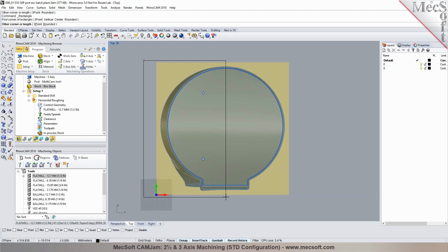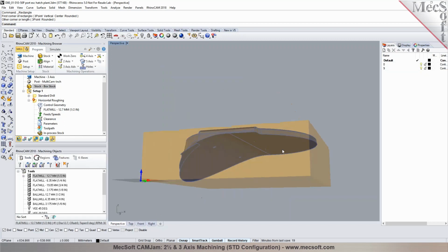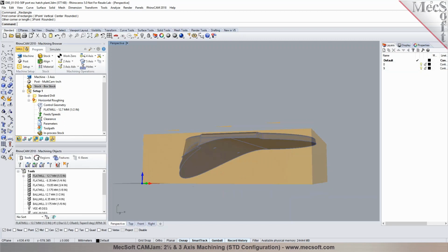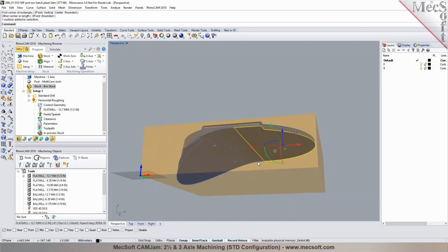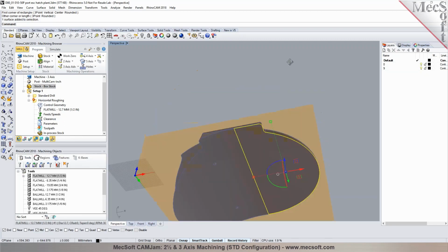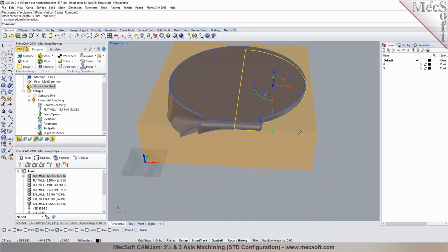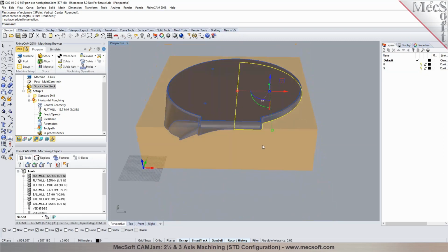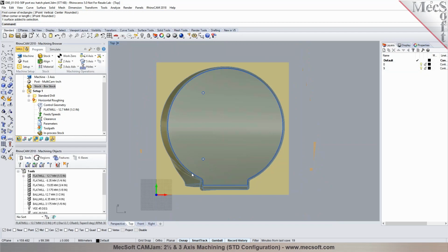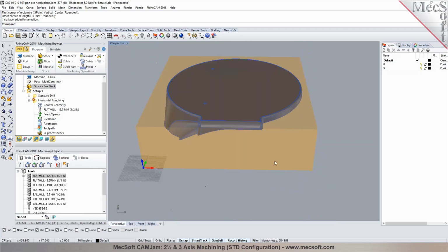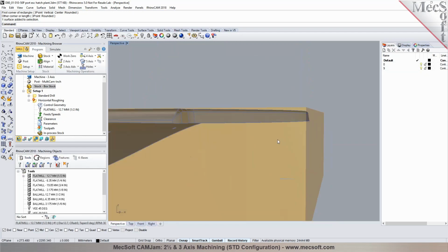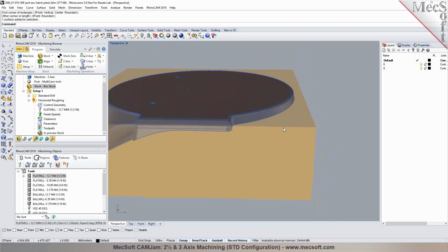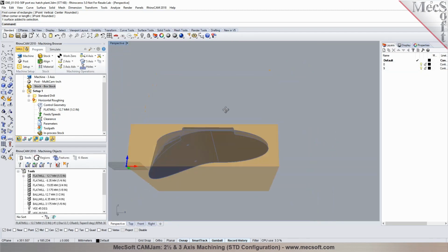The other thing you could also do is put a surface so you don't cut past a certain side from the bottom, because over here you have to machine this anyway from the bottom, right? So what I could do here is select that surface, and I can draw a plane, or I can put a rectangle in there. One of the ways you could do it is extend that out further, so you don't want to cut past that. You can even draw a simple plane in there.